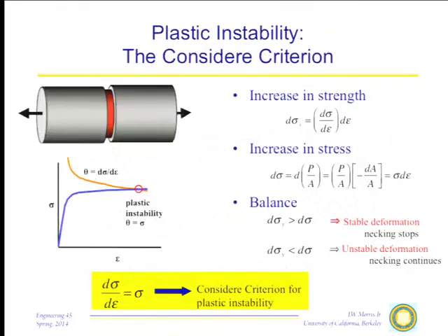Now, there's a fairly simple theory of how this plastic instability develops and when it occurs, which has the incidental property of telling us how to figure out where the ultimate tensile strength is from the true stress, true strain curve. Suppose we have a sample, and suppose it begins to deform plastically. Even though the sample overall is deforming uniformly, you've already seen that the incremental deformations are all local. What happens to the specimen is that when an element of plastic deformation happens, we get a little strain here, which will cause the material to deform locally.